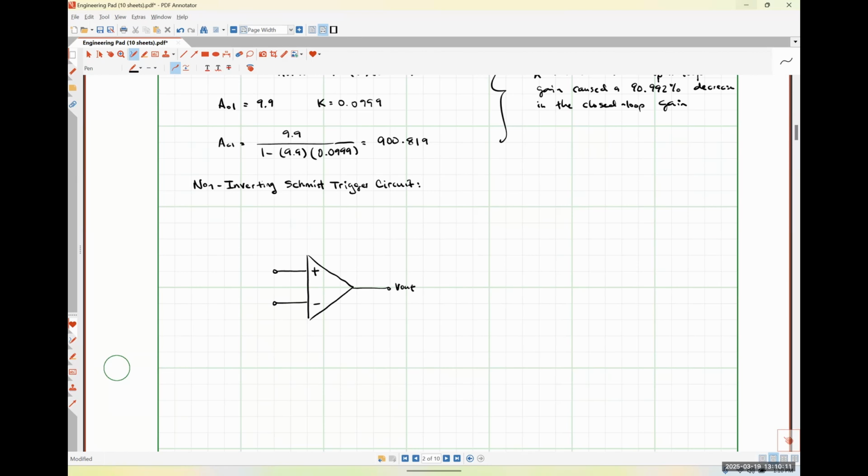So this circuit utilizes positive feedback, as we've been talking about. And so how I'm going to implement positive feedback with an op amp is I am just going to give myself a feedback path, or a conductive path, from my non-inverting input terminal to my output terminal, okay? So I now have feedback, okay? And in this case, positive feedback because I'm taking my output signal and sending a portion of it to that positive terminal. So that's what's telling me it's positive feedback.